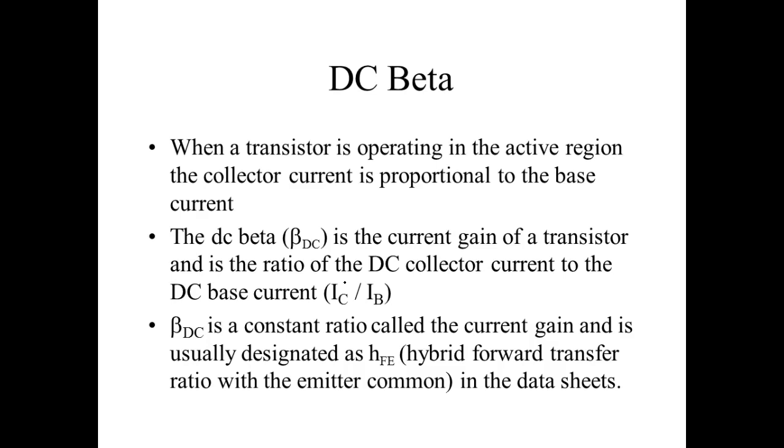Now remember, a transistor is a current valve. It doesn't control a voltage. It controls a current. Now we can run that current through a resistor and make it appear to be controlling the voltage, but the transistor is not controlling the voltage. It's controlling the amount of current. And then we use a resistor up there in the collector, right? You understand?